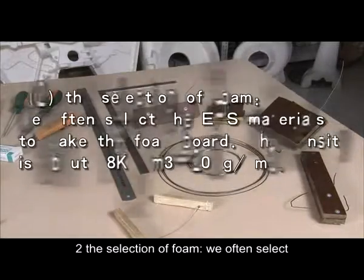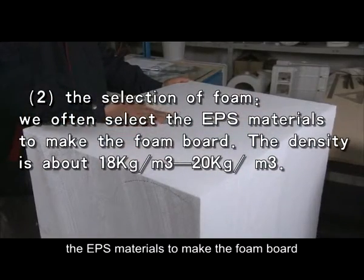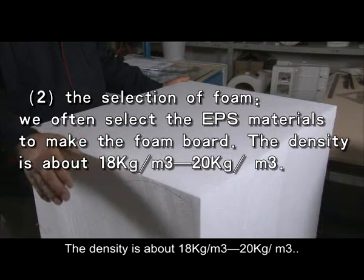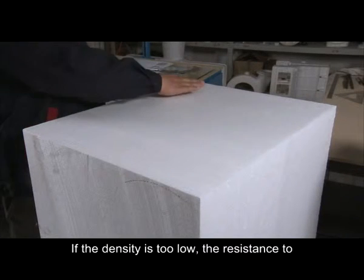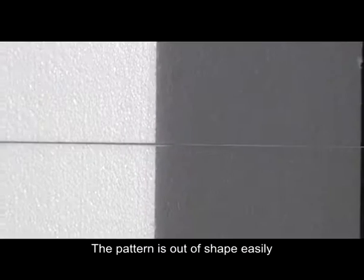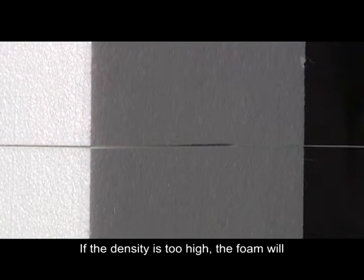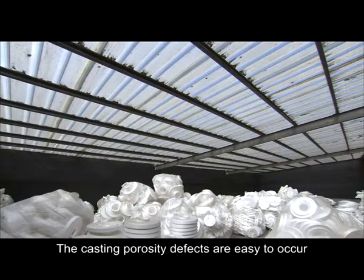2. The selection of foam. We often select EPS materials to make the foam board. The density is about 18 kg per cubic meter to 20 kg per cubic meter. If the density is too low, the resistance to bending will decrease correspondingly. The pattern is out of shape easily. If the density is too high, the foam will increase the gas bubble amount. The casting porosity defects are easy to occur.